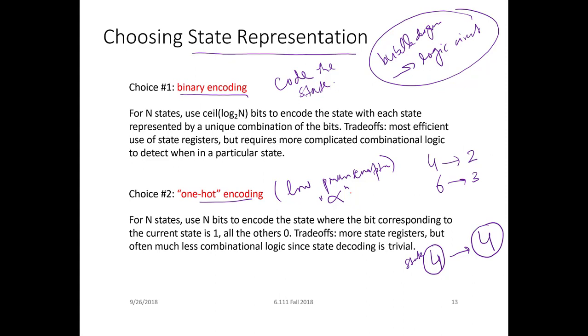And if you want to reduce the switching activity, you have to ensure that only a single bit changes. If 2 bits change, then your switching activity is higher. So 1-hot encoding is a scheme in which if you go from one number to the next number, only a single bit changes. But in binary numbers, if you go from one number to the other, multiple bits can change. And this multiple change of bits means higher power consumption.